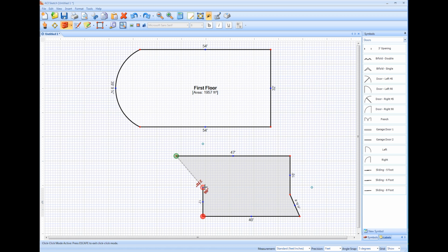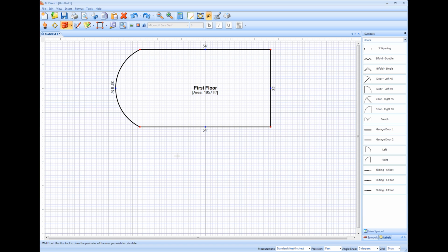If you realize you've made a mistake or just want to go back a few steps, just hit the delete key a couple times, and as you hit delete, it reverses those steps. To redo, it's insert. So by hitting insert and delete, you can trace or retrace the last few steps you had drawn. If I were to delete this all the way out, I can resume drawing using the keyboard in the same principle. Place your mouse cursor where you'd like to begin the wall,